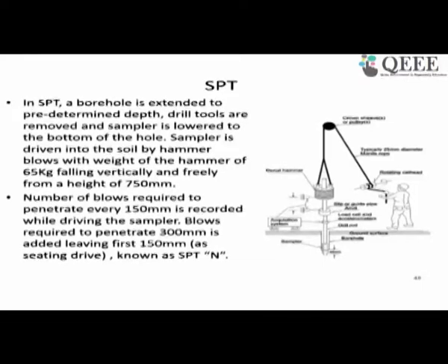What exactly we do in this test is we use a borehole which is extended to a predetermined depth, and the drill tools are removed. Once you reach a particular depth of the soil, we remove the drill rod and attach the bit with the sampler.